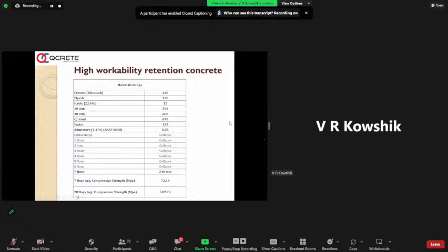These things were unheard of earlier. It would have been very difficult to imagine a 7 hour slump retention in earlier days. In fact, many concrete technologists were resisting this move because if somebody gives a retention of 7 hours, there can be tampering of concrete.